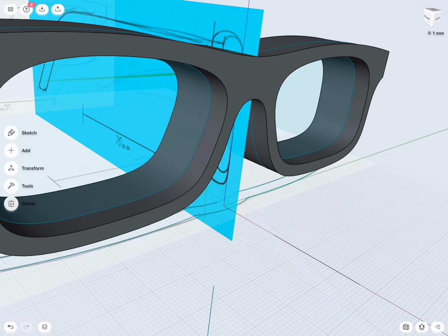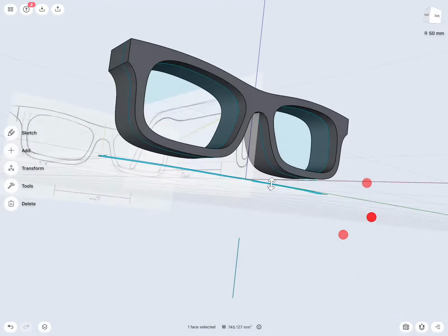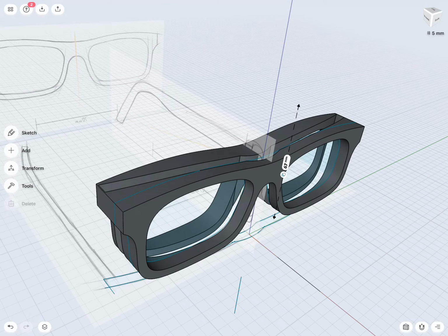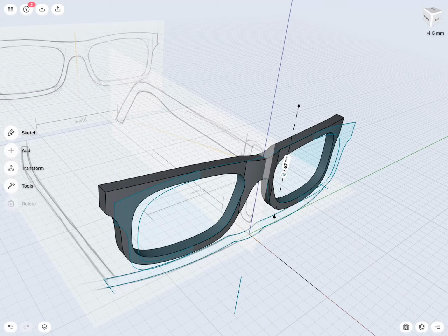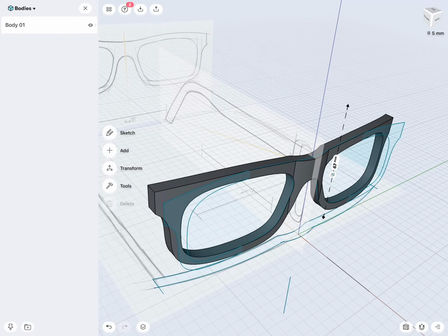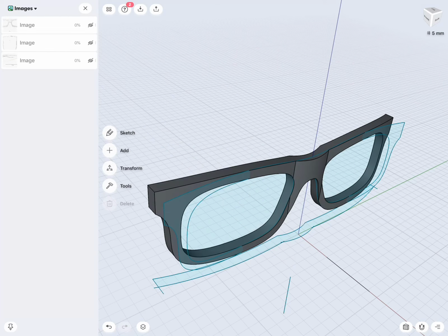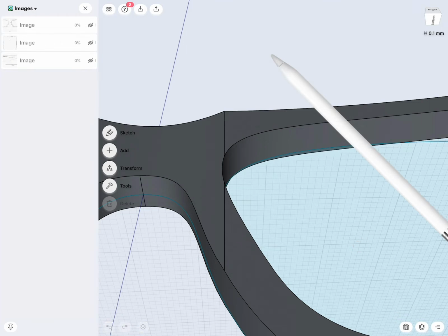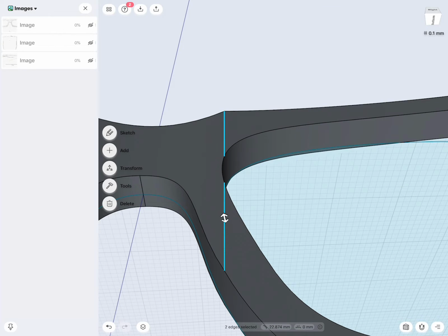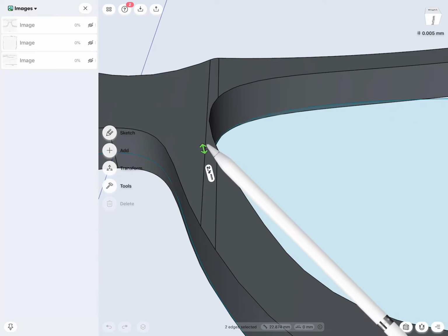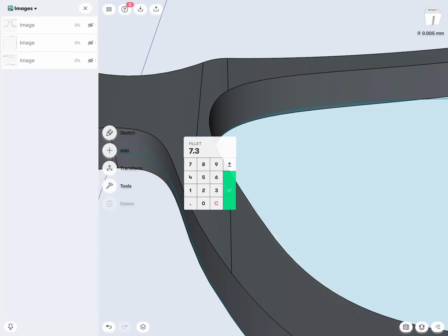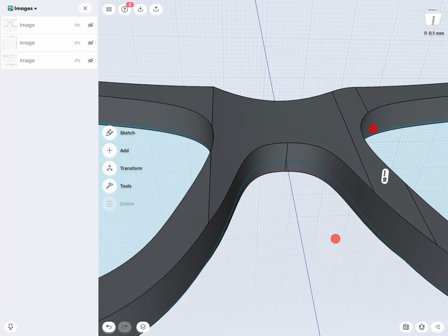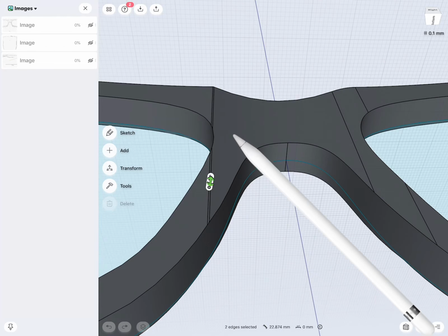And now select this filled area. We drag it up, and instead of cutting through it, what we will do is we will select intersect. And let's hide actually these images. And there you see what we have. Very good. What I do not like is right there, this edge and this edge. They're kind of sharp. So what happens if we fillet them? So maybe a 6. Let's say this is where my face is, so we give this a 10. Good. Now we can do the same here.